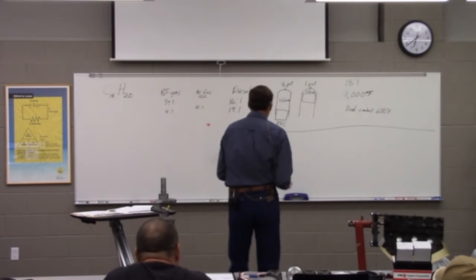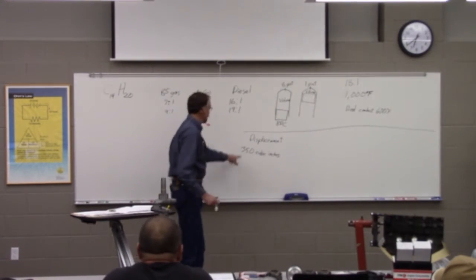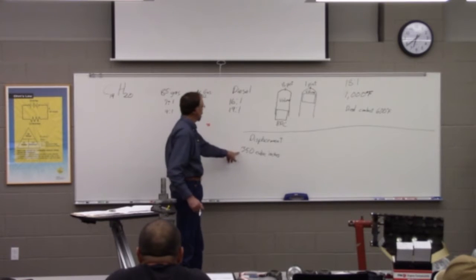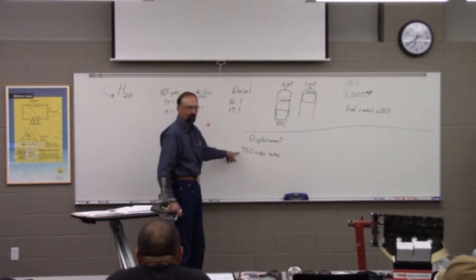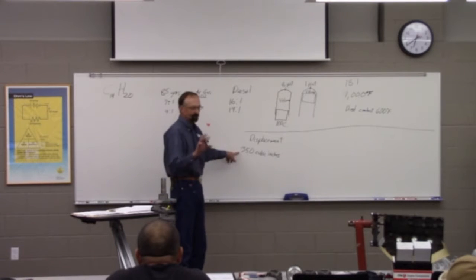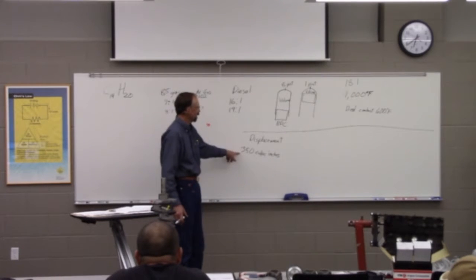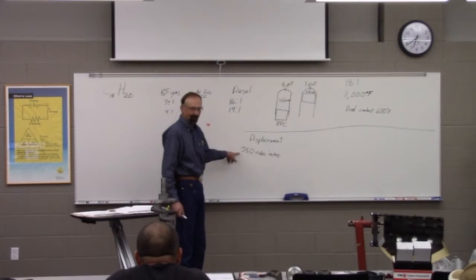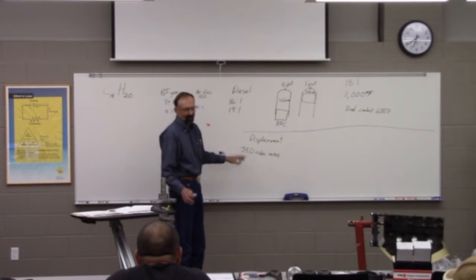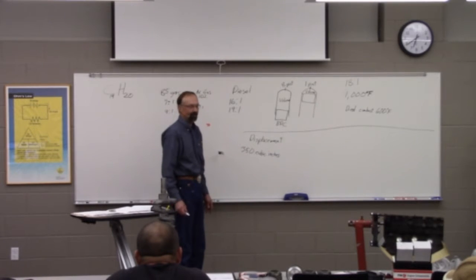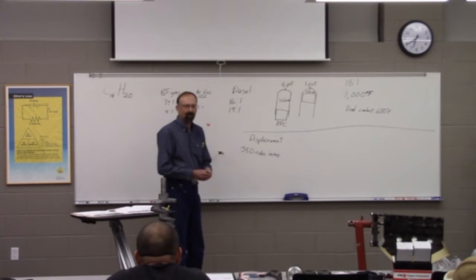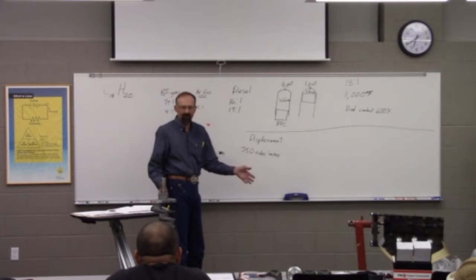It's really not telling us, there again, okay, you can have a 350 that's running 7:1 compression and running a small cam and makes 185 horsepower, or you can have a 350 that's running 10:1 compression and a big camshaft and making 400 horsepower. So it's not as valuable of information as a lot of people like to think it is, but it does give you a little bit of an idea how big the engine is.